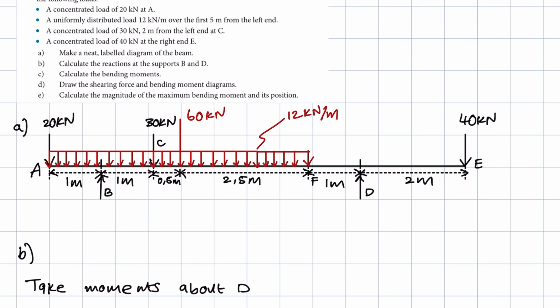Now, it is good to note that if you're looking at either a simply supported beam or an overhanging beam, the bending moment at the ends of the beam, so on the right hand end as well as on the left hand end, is always equal to 0, right? And the reason for that is because when doing bending moment calculations, you can either consider forces on the left of that point or you can consider forces on the right of that point.